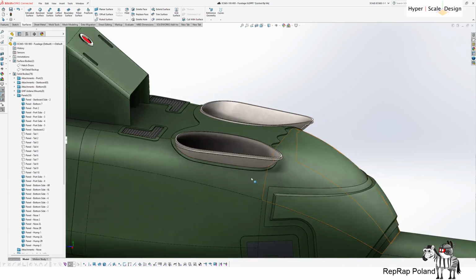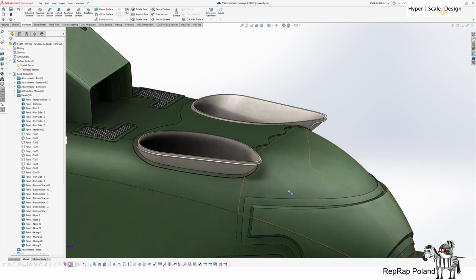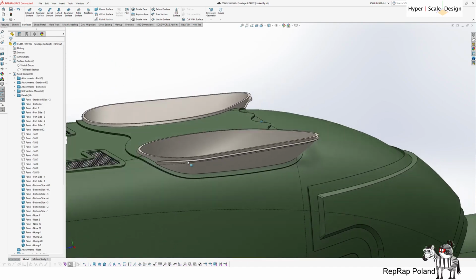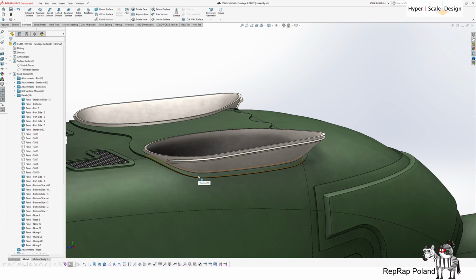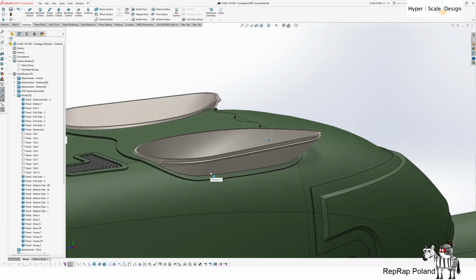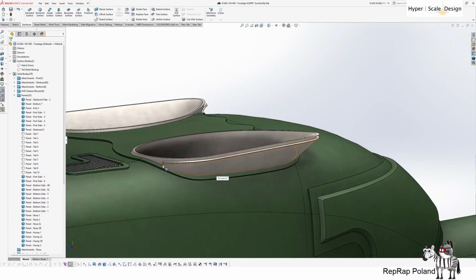First of all, the surface itself where the panel resides is across multiple faces, and each of those faces was lofted. So the faces are tangent, but it's still multiple faces. And what I actually wanted to do here is to have a panel that goes along the exhaust pipe, and it's fixed width. So here it's 24 millimeters all across the feature on the surface.